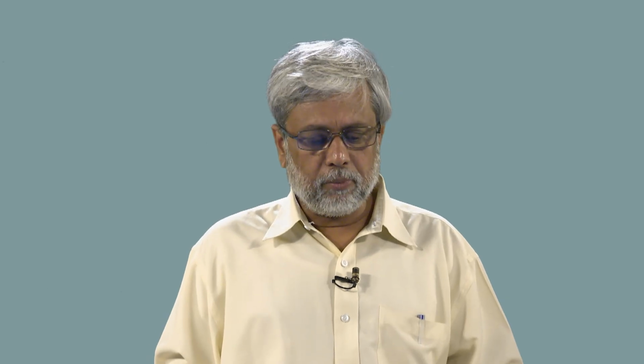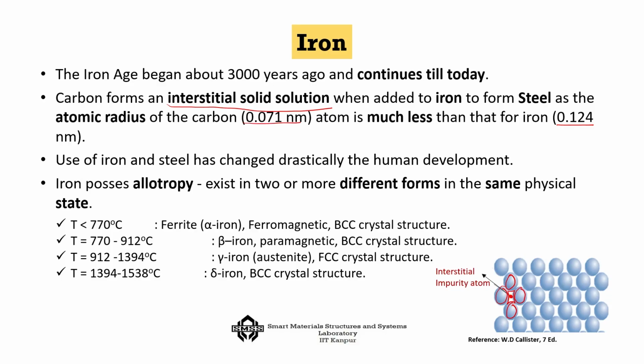Now, iron, however, possesses many different allotropes or forms. Okay? For example, when the temperature is less than 770 degrees centigrade, we get iron as ferrite, alpha iron we call it, which is a ferromagnetic BCC crystal structure. From 770 to 912 you get beta iron, which is a paramagnetic BCC crystal structure.